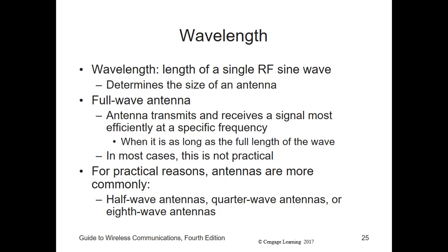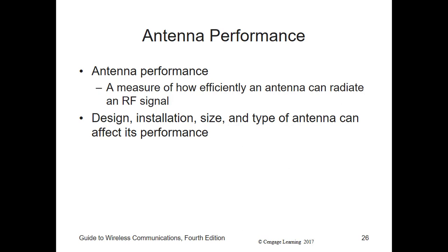Alternatively, if the antenna is much longer than the wavelength, it will send out some RF energy, just not efficiently. And this may affect the reliability of the transmitter circuits as well. Now, in antenna design, certain items such as fasteners, brackets, and support structures can affect the way the antenna emits